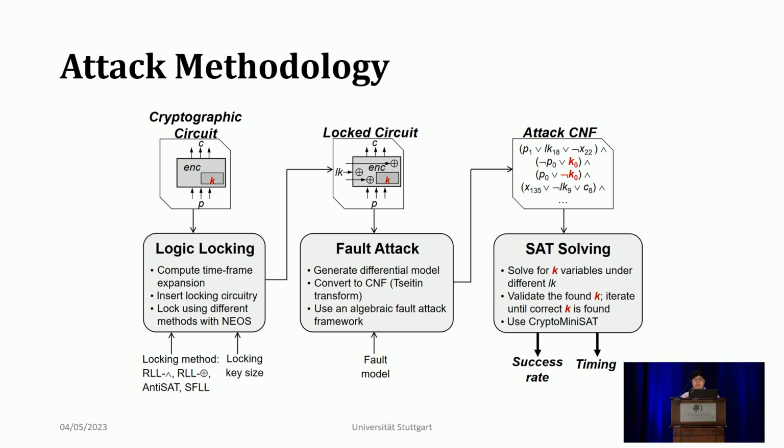We then perform a differential analysis on these different encryptions in the presence of faults and the absence of faults. For LEDA, there are no fault injections. We simply perform differential analysis on multiple circuits that have been unlocked using different randomly generated incorrect logic locking keys. This attack formula is then converted into its conjunctive normal form using Gaussian transform and is fed to a SAT solver to solve the attack formula for the secret cryptographic key.